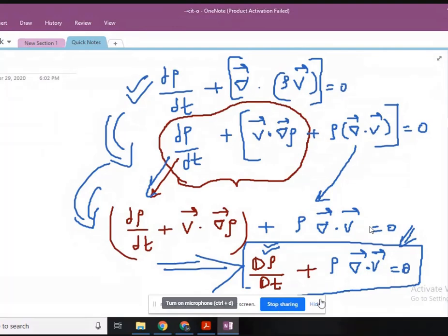On looking at an equation, you should be able to tell whether it is a conservative form, non-conservative form, or what type of equation it is. Have they followed a control volume approach or control mass approach? Is it eligible to be applied for a CFD code or not? Is there any difference in using this set of equations for your problem or not? This sort of equation is good for incompressible flows, but if you use the same set of equations presented here for compressible flows, you'll get completely wrong results.